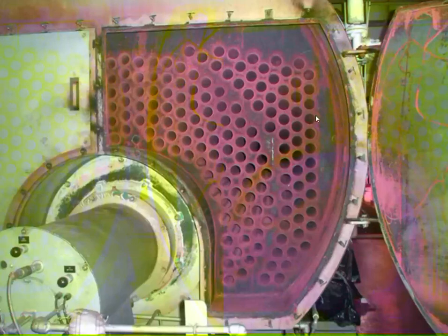Now, one disadvantage of fire tube boilers is that you cannot soot blow. It doesn't work very well because of these long tubes with the carbon inside the tubes. So on occasion, if you are burning a dirty fuel, such as heavy fuel oil, you would have to clean these tubes. It's done with a brush, and the operator stands on this side and runs a brush all the way down through the tubes.